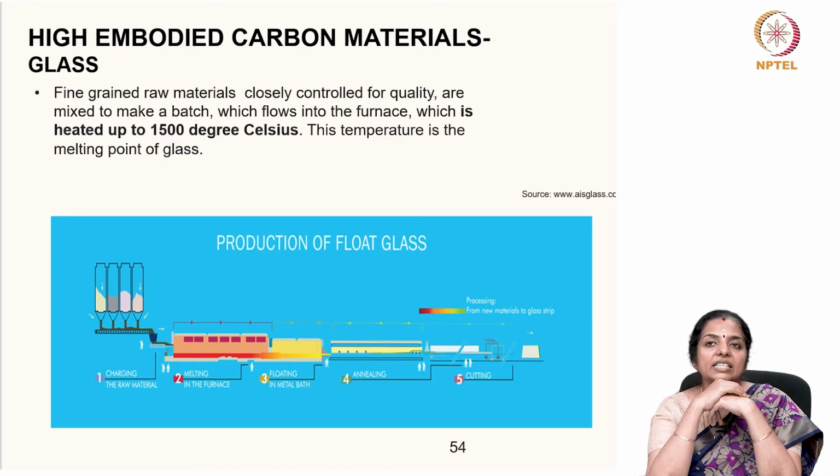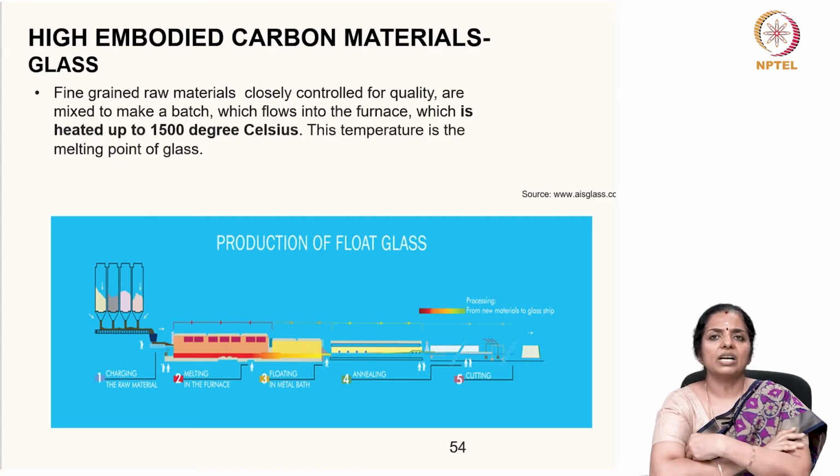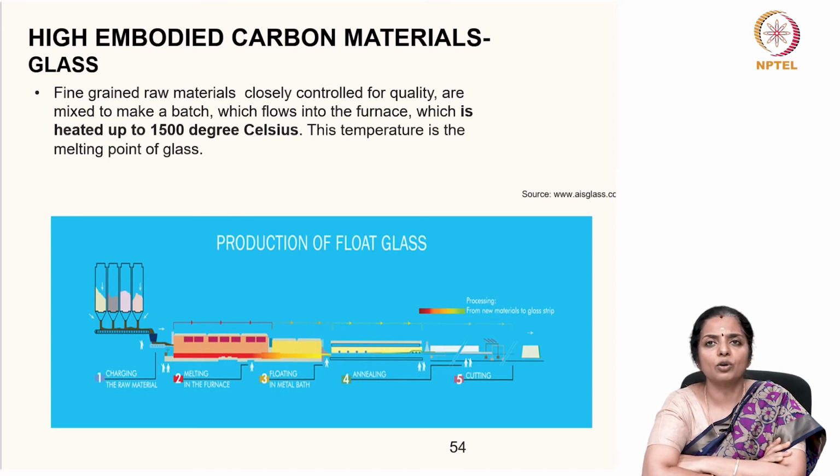Glass from the furnace gently flows over the refractory spout onto the mirror-like surface of the molten tin, starting at 1100 degrees Celsius and leaving the float bath as a solid ribbon at 600 degrees Celsius. Coatings that make profound changes in optical properties can be applied by advanced high temperature technology to the cooling ribbon of glass. Despite the tranquility with which the glass is formed, considerable stresses are developed in the ribbon as the glass cools.